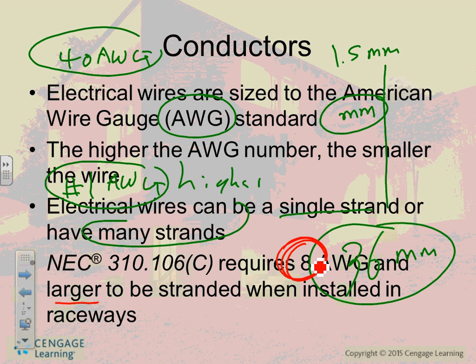Yeah, when they do these, they have steel in the middle, and you've done a lot of them, haven't you? They have steel in the middle and aluminum or some type of alloy around it. Anybody know why they have steel in the middle? The weight. Yeah. Remember, you're stringing them between poles and wind. So for physical, mechanical strength, they put steel in the middle of them to hold them, and they wrap all this aluminum conductor around it.